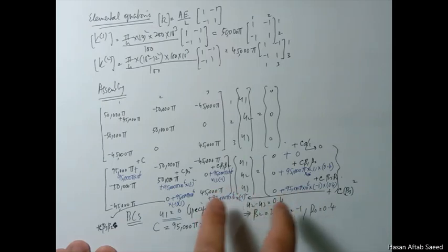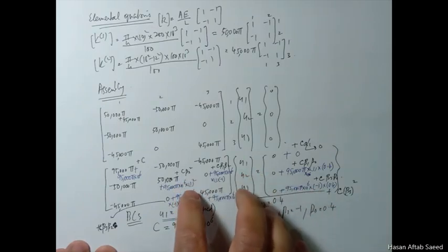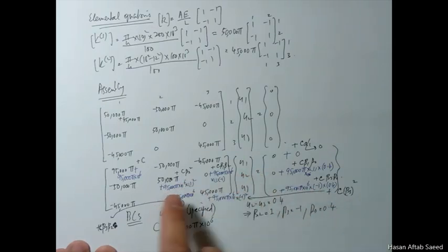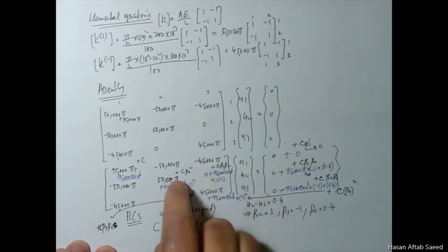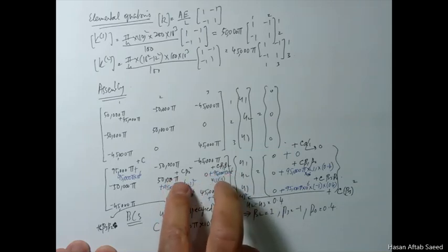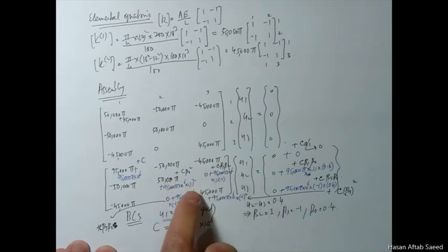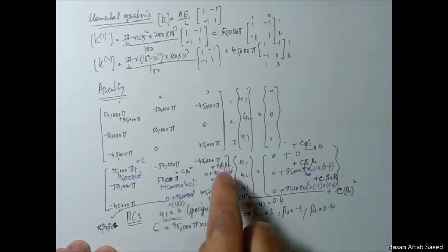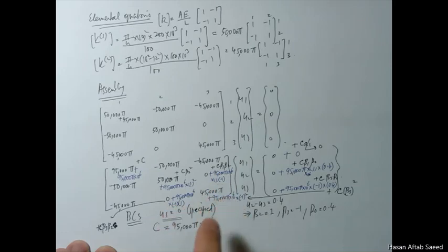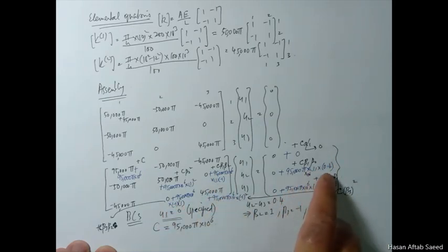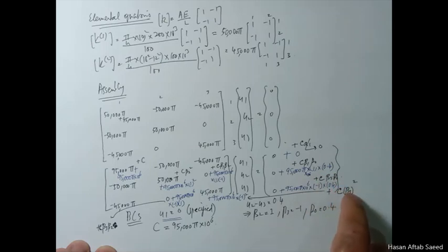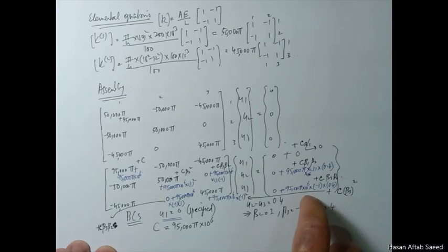So the difference between these 2 and 3, these are multi-point constraints, you apply not only on the diagonal terms but also off diagonal terms, and there is some squares involved. On diagonal terms, square of the relevant beta. On the off diagonal term you have the product, and on the right hand side also there is a product between the beta naught and beta 2 in this case, beta naught and beta 3 in this case.